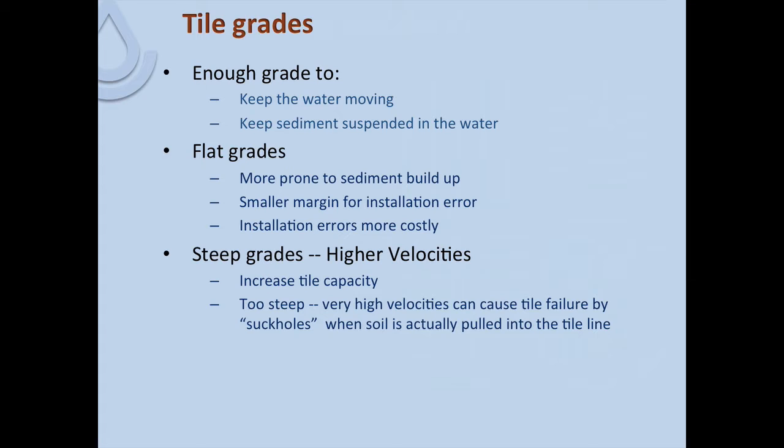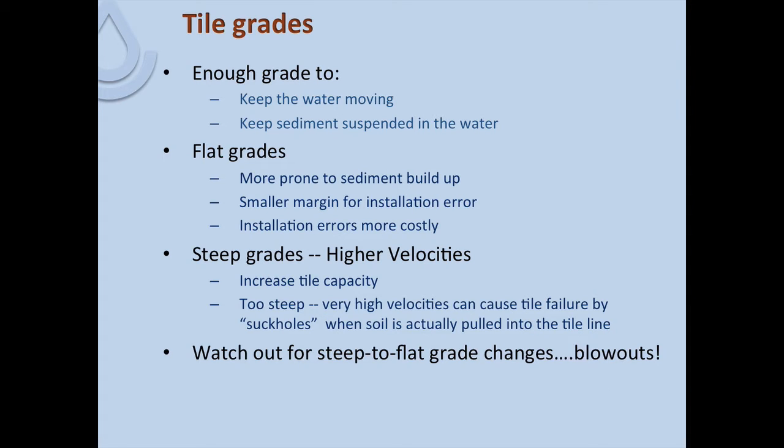We need to watch out for steep to flat grade changes, and so where that grade changes by an order of magnitude, say going from 1% slope to 0.1% slope, or 2% slope to 0.2% slope, where we get those types of grade changes, now we're creating high pressure, where that high velocity water goes to flatter grade and becomes low velocity water, and we get a pressure increase, and so that can create blowouts.